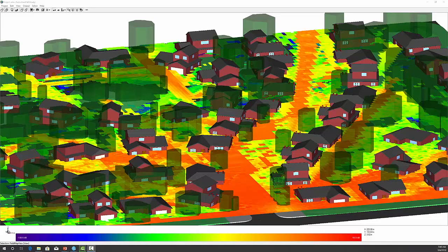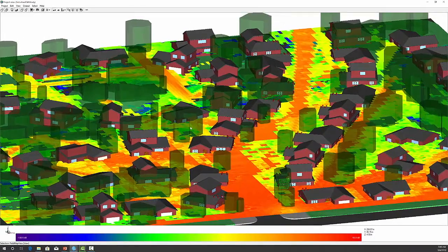So as an initial set of simulation results, we placed a dipole where the transmitter is and ran a quick simulation to look at fields to see how the fields propagate. This also creates a baseline scenario. We start with a dipole and then we can see how much improvement we get when we start using beamforming with the MIMO antenna. So on the screen we show the field map results overlaid on a view of the scene. And we're actually looking at Wireless Insight right now, looking at some of these results.